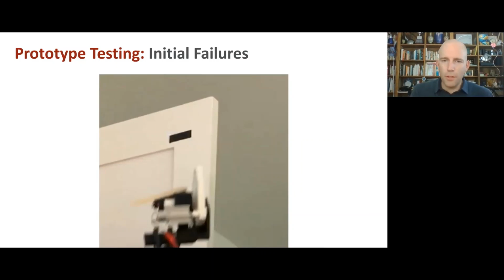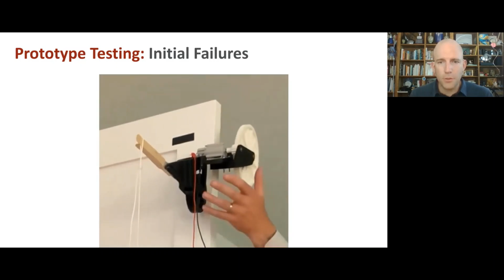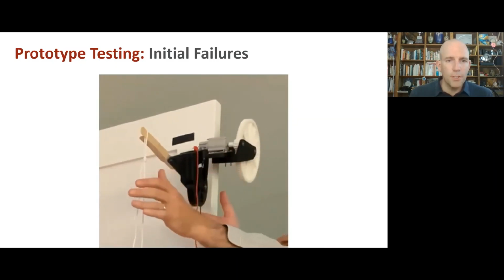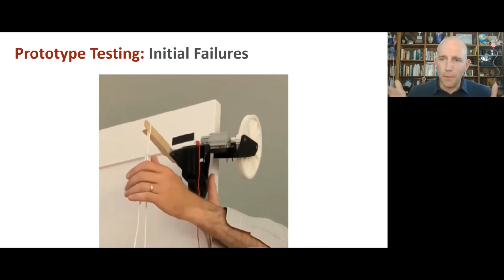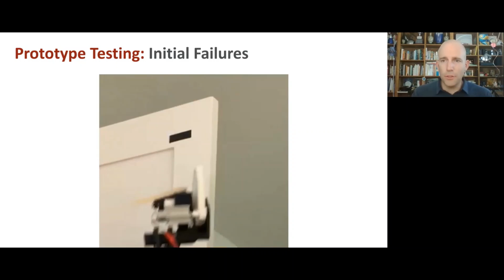And so after playing with making these adjustments, and you can also see that the lever arm is extended here with popsicle sticks with this sort of janky I-beam or L-beam here, because as the wheel started to rotate, the effective coefficient of friction was much, much lower than when we hung the system on the door, and needed to increase that lever arm of the payload so that this length divided by that length was less than or equal to the apparent coefficient of friction.